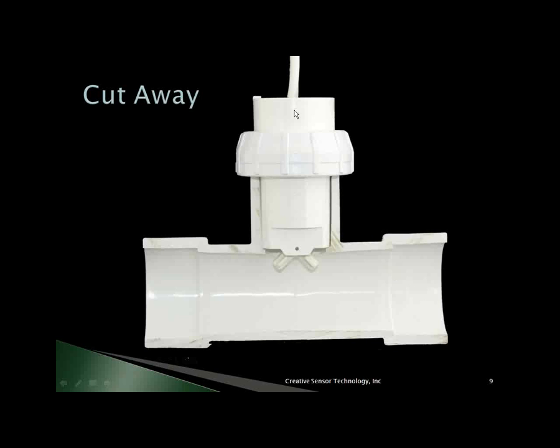And then the detection system is this insert assembly that goes down through the branch of this custom T. These two little blades that you see here are part of the impeller that is spun by the water that goes through this T, and this impeller's spinning rotation is detected by a set of electronics that are housed inside this assembly.